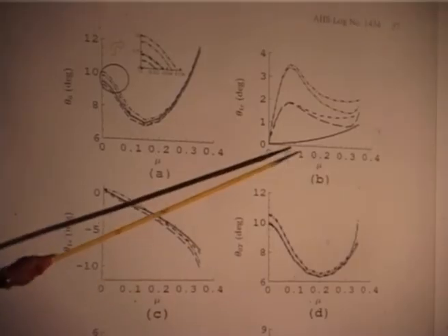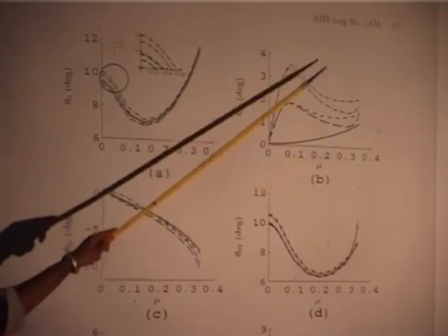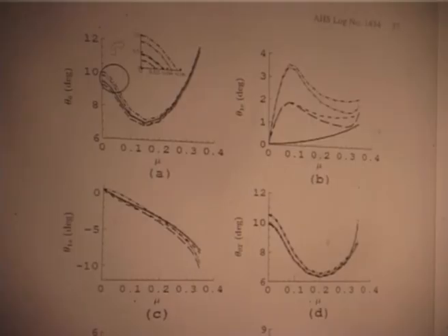This was a point of debate. Why the helicopter? It is like this. The pilot wants to fly forward. Usually the general tendency is what? If you want to go high speed, you give more angle. But here, initially you give more angle, then as you increase the speed, you start decreasing the angle. So from hover you go to very large and then you start coming down. This defies the traditional convention.